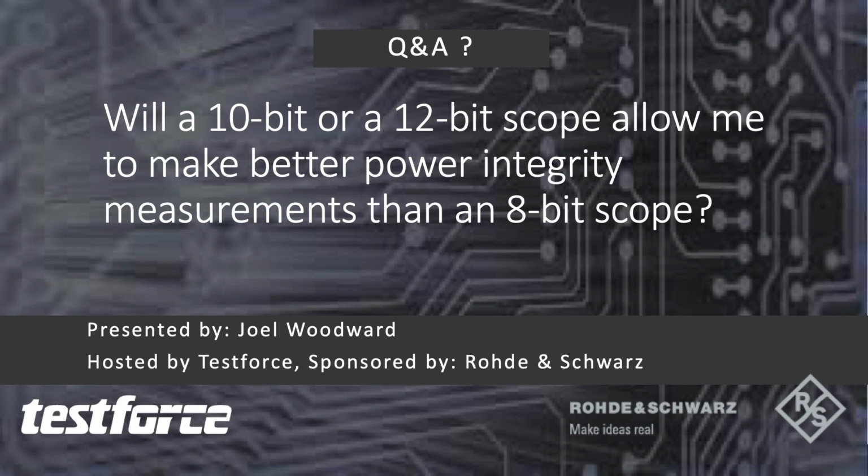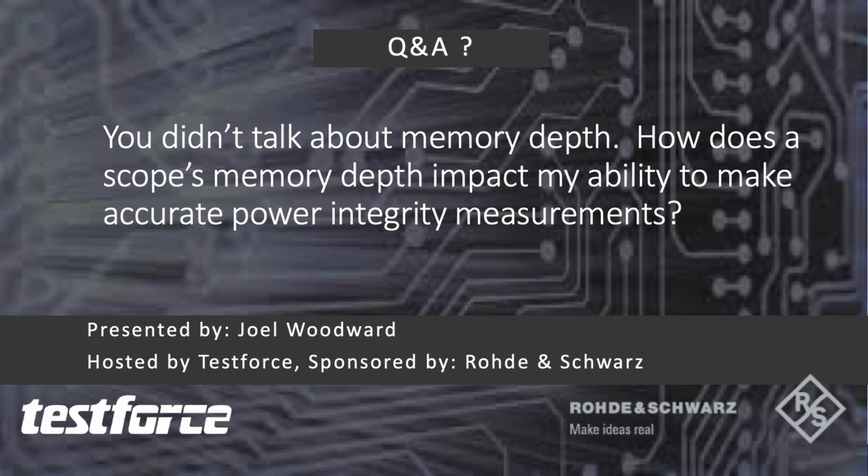The second question is, you didn't talk about memory depth. How does a scope's memory depth impact my ability to make accurate power integrity measurements? Memory depth allows oscilloscopes, greater memory allows oscilloscopes to capture more time. The other benefit that deep memory has is the ability to maintain a higher bandwidth with slow time base settings. So you can think about an oscilloscope as you turn the time base slower and slower to collect more information or more time, which is consistent with power rails that typically need a lot of time.